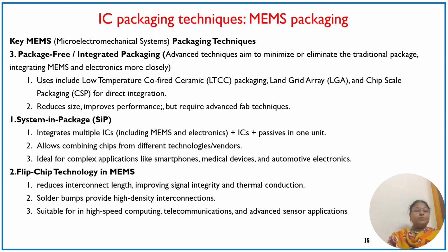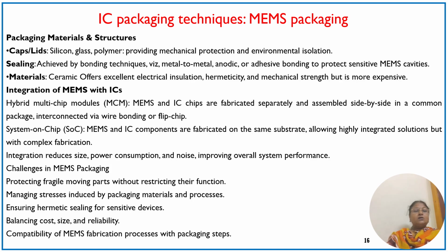Flip chip is the latest technology which reduces the interconnect length, improves signal integrity, and also thermal conduction is possible. Solder bumps provide a high density interconnect and it is suitable for high speed computing, telecommunication, advanced sensor applications.